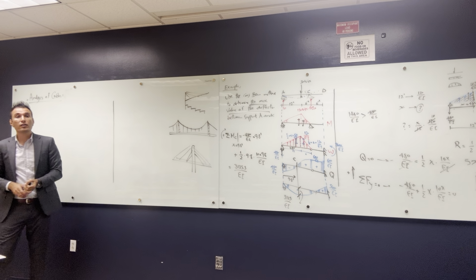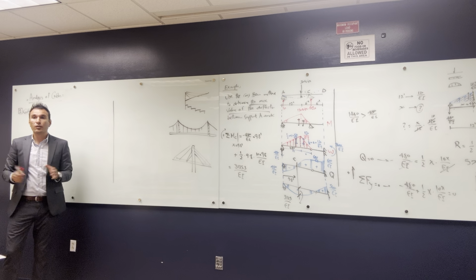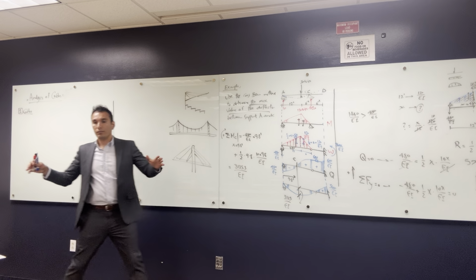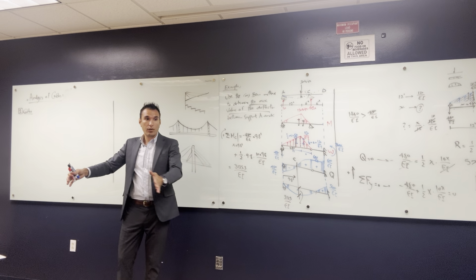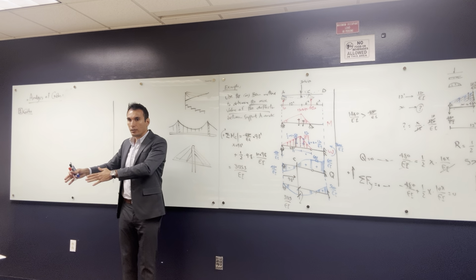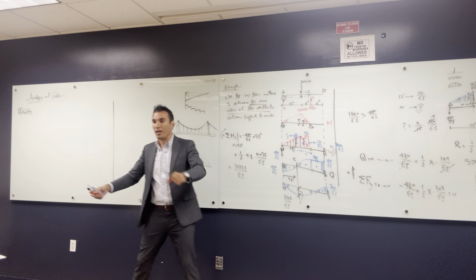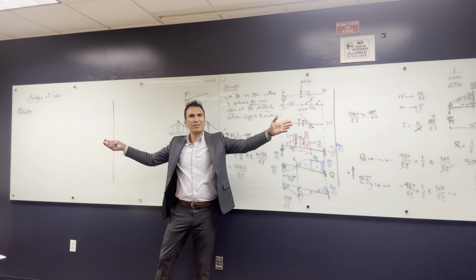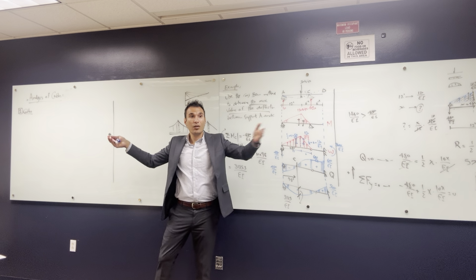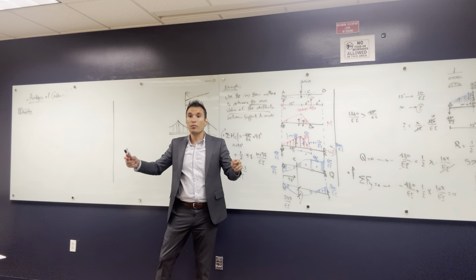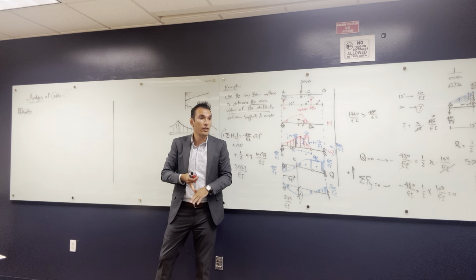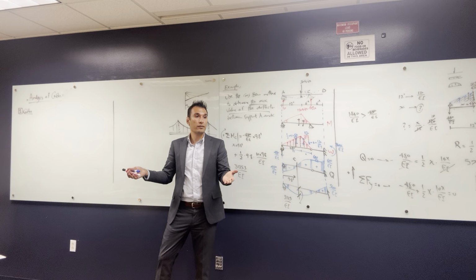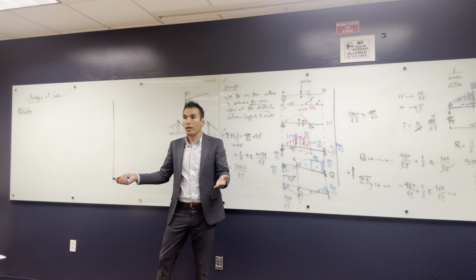And also, there's one application of cables that we see every day when we drive our cars. Like the power network, right? You always have a transmission line, and the transmission line has a tower, and there's a cable that runs from this tower to this tower. You'll tell me, but this is not a structure, this is what? No, it's a structure. Structural engineers study how this cable performs against wind, against tornadoes, against earthquakes. I tell you what loads are on this cable: its own weight. The own weight of the cable is a load, right?